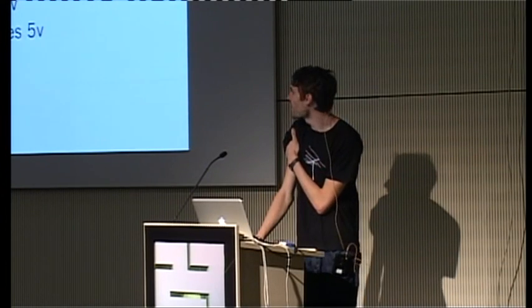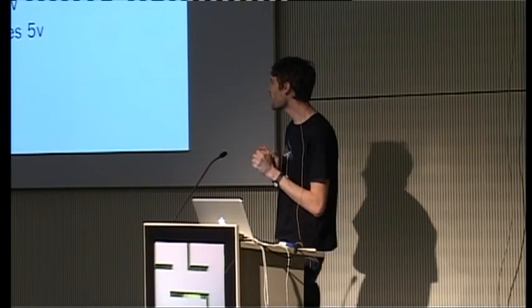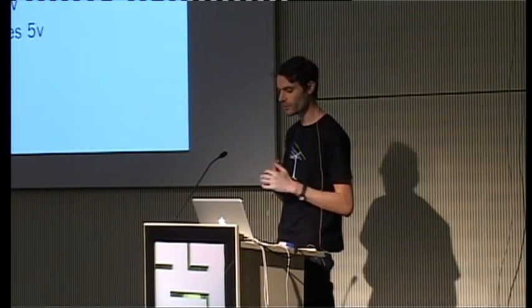And so let's take the first, which is serial. With all of these, I like to look at the electrical characteristics of the actual pins when I'm looking at a device and I have a set of, let's say, 40 pins. I would like to reduce the set a bit so that I don't have to check them all. So it can sometimes be helpful to check the voltage or resistance and things like this.